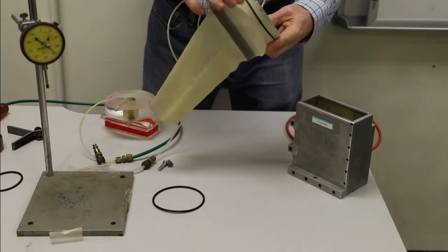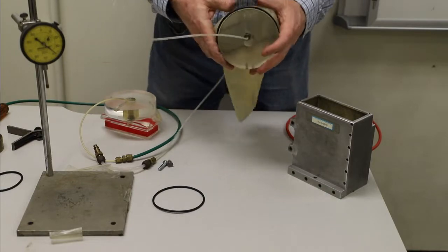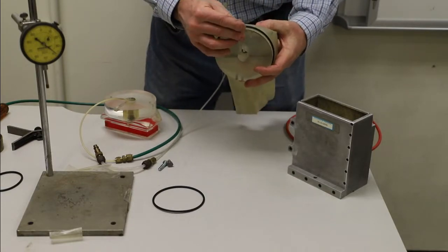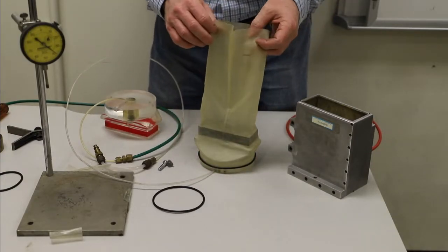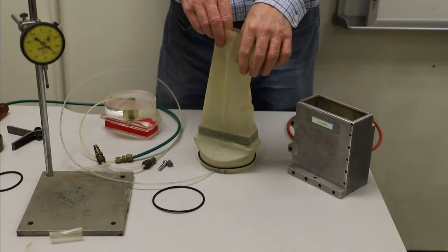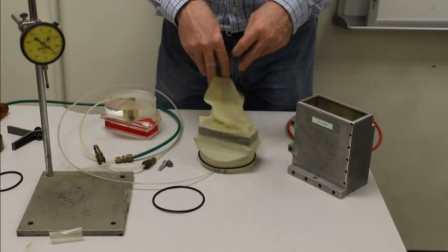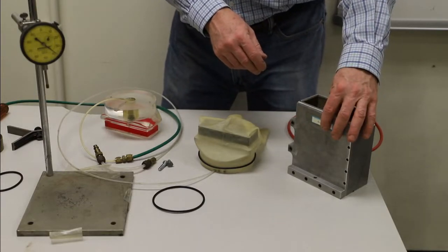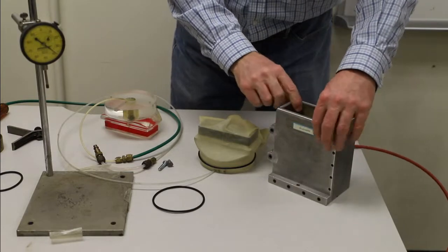Put that O-ring on. Make sure it's over the membrane everywhere, and that'll help keep the vacuum pressure inside the specimen separate from the atmospheric pressure here in the room. Alright, and so now we have a similar sort of a mold. It doesn't come in two separate halves. Instead it has a hinge in the back corner.